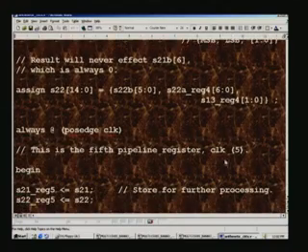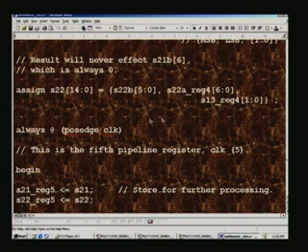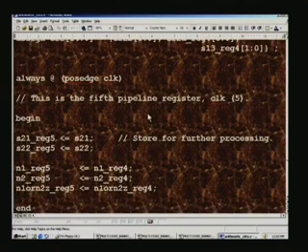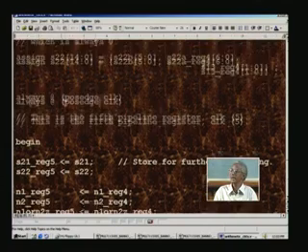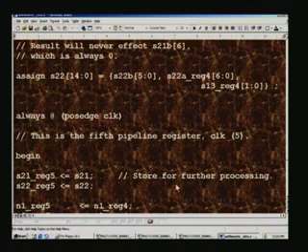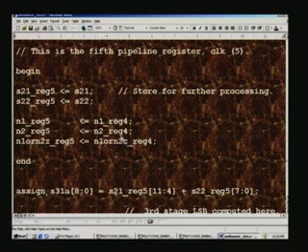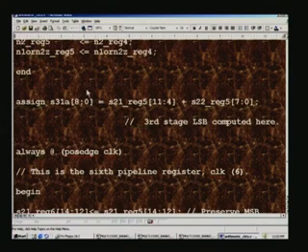At clock 5, so far we have seen clock 4, and what happens here, this is the 5th pipeline, and we need to once again store some of these values. For example, S21, S22 are what we have just now processed here, the second stage partial sum, and we also need to store the 0 value or the 2 sign bits, and then process further. So, at this stage, the third stage LSB is computed here. In this third stage the final output is going to be this, whereas the second stage output, which is this one, is being taken here.